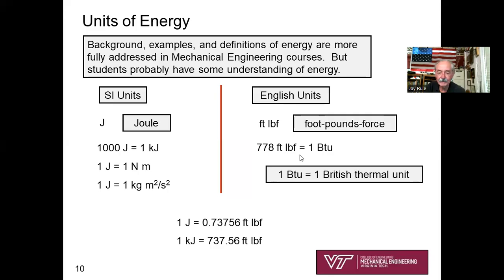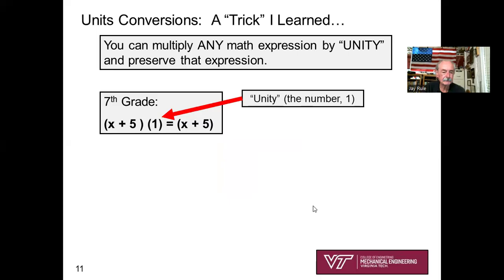I'll have to apologize and say you've got to commit this to memory for speed in doing your homework, quizzes, and tests. 778 foot-pounds force equals 1 BTU. You've got to get that into your head. That'll save you a tremendous amount of time in problem solving in this class.